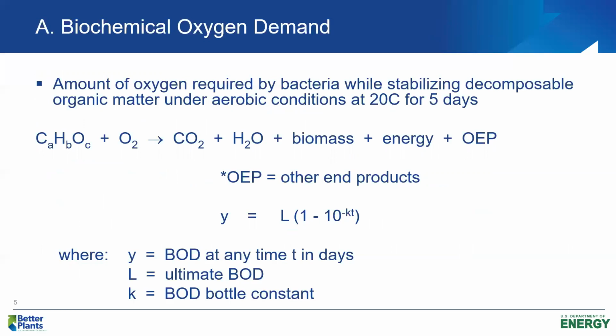Well, arguably, the most important parameter when we talk about municipal wastewater treatment, as far as defining the quality of the wastewater, is biochemical oxygen demand, BOD. In my opinion, it is the most important parameter we deal with, because BOD measures the biodegradable organic content of the wastewater in terms of oxygen equivalents.